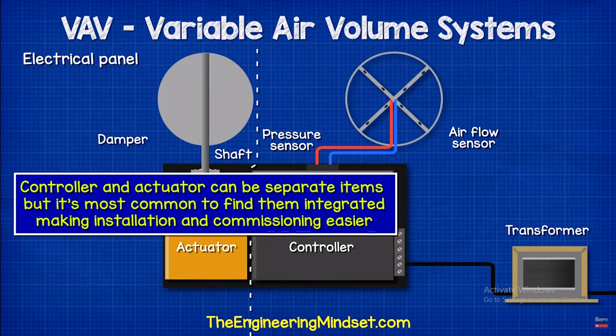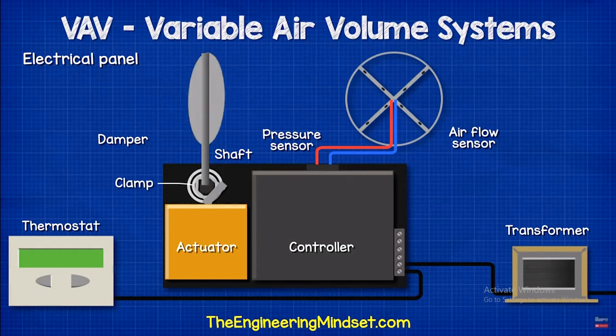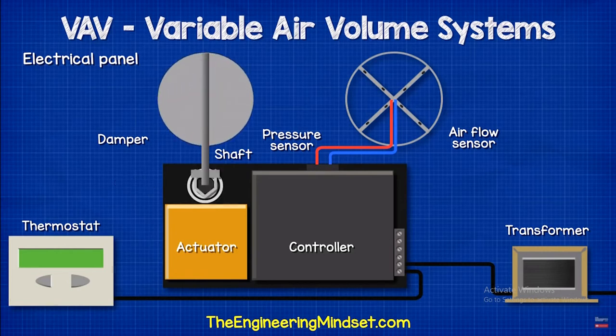The damper doesn't usually fully close. That's because we still need a certain amount of fresh air to enter the room. So it partially closes, which allows a small stream of air to trickle past into the room. If the thermostat detects that the room temperature has increased above the desired set point temperature, then the damper is instructed to open further and allow the cold air to enter. Remember, this air is around 13 degrees Celsius or 55 degrees Fahrenheit, so that will cool the room down fairly quickly, and the warm air will be sucked away through the return duct.